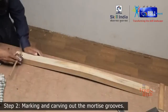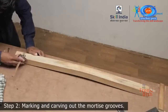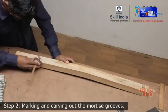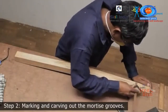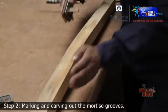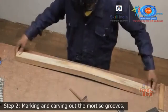Adjust the mortise gauge and scribe 2 lines for the mortise groove on the back leg, leaving a 12 mm gap from the top edge on the inner side for the backrest. Then, leaving a gap of 70 mm from the bottom, mark 1 mortise groove on the front face for the bottom rail. Similarly, mark 2 mortise grooves on the front face and side face at the center of the leg for the framing pieces.